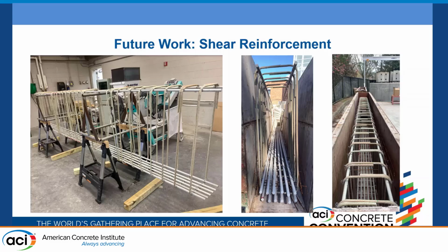I have a question. It's not your research, but why were they putting horizontal stirrups in the region of the beam? Just for fun? I think to meet the requirement. And how were they anchoring them? Because these ones go around the reinforcement. They just had long overhangs like the longitudinal reinforcement, I suppose. So they were like skin reinforcement in a sense, right? And they didn't work that well. No, it lowered the capacity a little bit. Yes, because now you have additional tension from the additional reinforcement through your strut. Oh, okay, interesting. That makes sense.